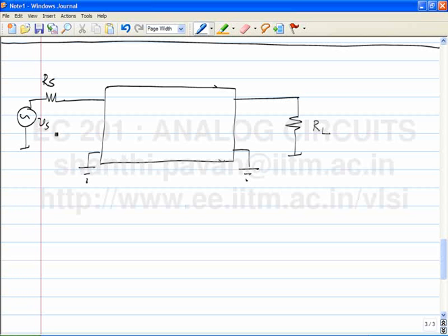That also has the practical advantage that even when you replace the source, for example, this PA system has got an input port and an output port, you want to be able to use many kinds of microphones, and the gain or the volume setting shouldn't have to be changed every time you change the microphone, and different microphones are likely to have different output impedances.